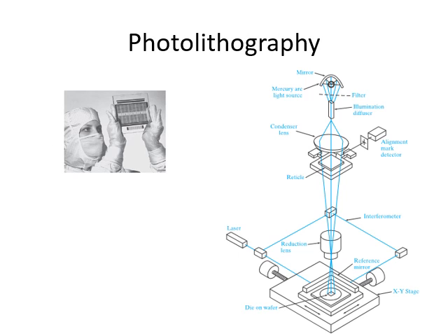As a part of revision, let me quickly summarize what we have seen in the previous lecture. We have seen photolithography, the process of applying the photoresist on the silicon dioxide. So this is silicon dioxide, and this is photoresist, and then using the mask and through the mask applying the UV radiations.